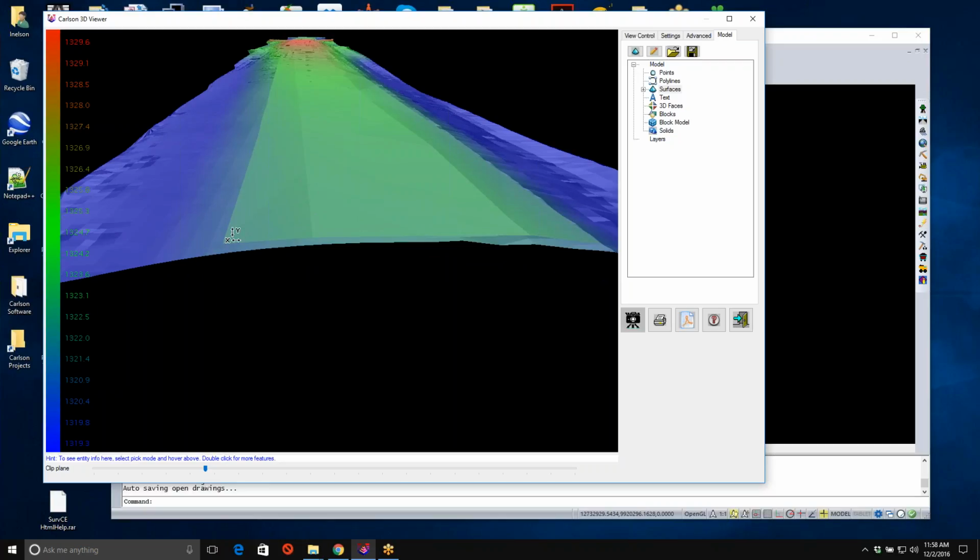So what I want to do to merge these two things together is create a series of slope projections from the shoulder edges of my roadway model to the LIDAR model at a presumed 3-to-1 slope, a very common slope for fore slopes on roadway designs. What we'll do next then is make that new surface model that will have the daylight lines so that these things will tie together. So I'm going to exit out of my Surface 3D viewer.